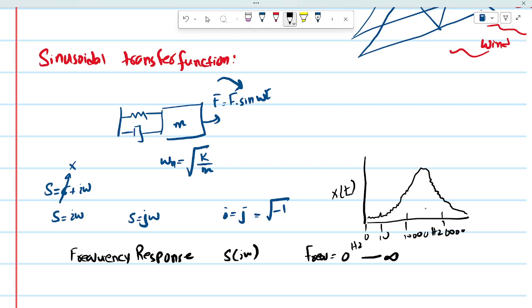So we will have a holistic view that this frequency range is dangerous for my system. If the excitation force is in this frequency, my system will likely undergo high amplitude of vibration, which may damage it. It gives us a picture of the safe and unsafe frequency ranges for my system.